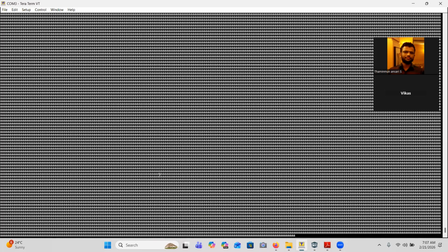The software that we have on our laptop is communicating with the microcontroller via a hardware cable, a Prolific USB to serial port interface. So now my laptop acts like one serial device, and the microcontroller board, the motherboard that we have now, acts as another serial device.